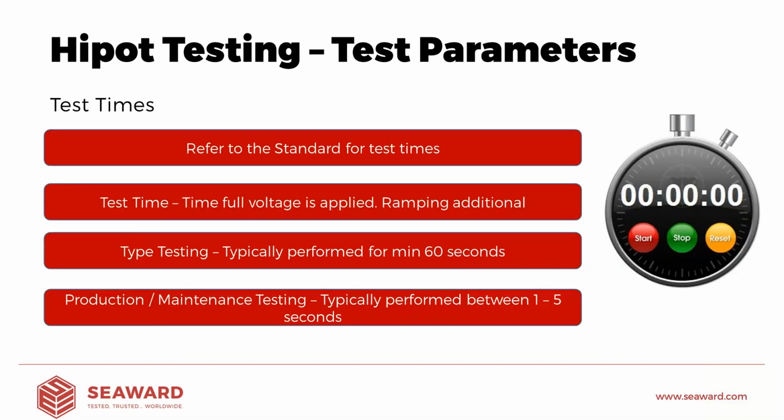Okay, test times. Always refer to the standard again for any specified test times. But as a generalization, always make sure that the test time is the full voltage time that you're going to run the test for. We'll talk about ramping of voltages a little bit later, but any ramping or discharging of the voltage should always be in addition to the full test time.